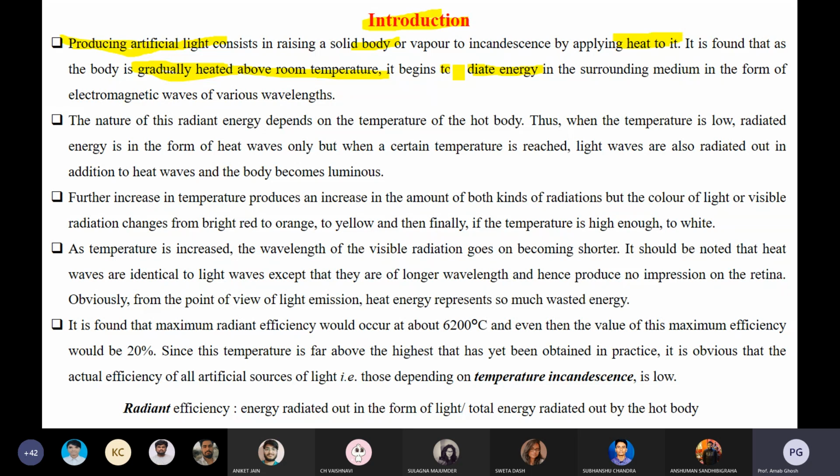Suppose you are using an insulator. How do you know the health of the insulator? You are just below the tower, and how do you know the health of the tower insulator? It's not possible to touch it and understand. So that's why you use the hotspot camera to see the heat distribution of each individual insulator.